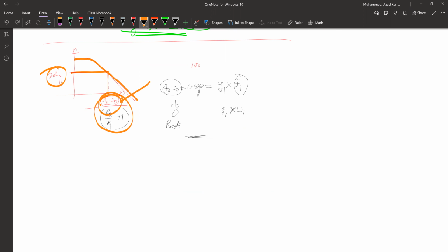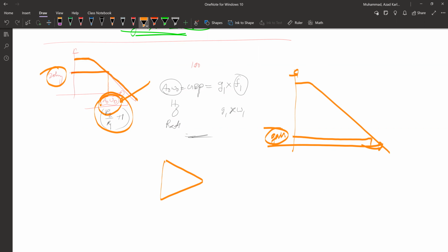Now what if I want a very high bandwidth? I basically have to operate at very small gains, correct? What is the workaround for this? How can I have higher gains and also higher bandwidths? What you do is take this op-amp and put it in cascade. That way, the bandwidth is higher and the resulting gain is G1 times G2.